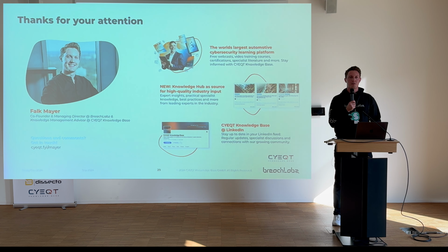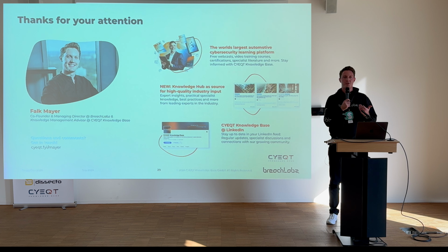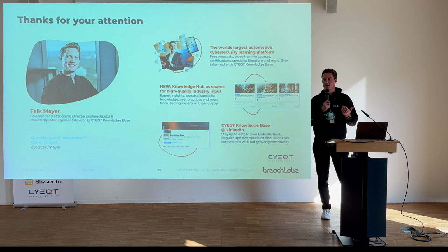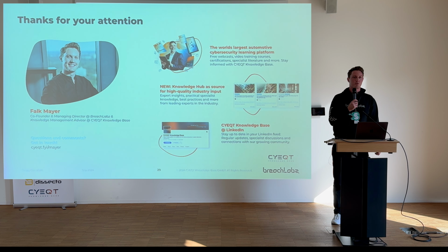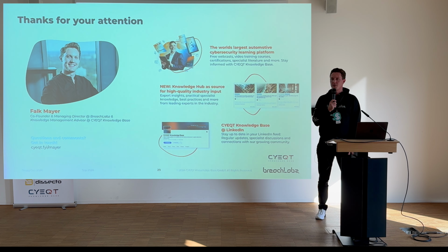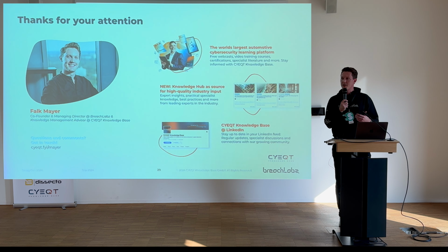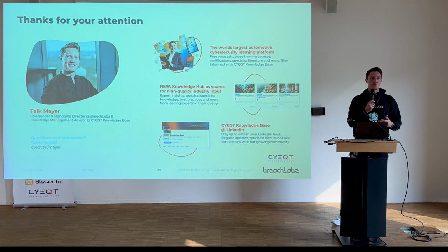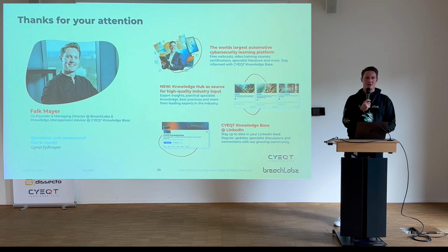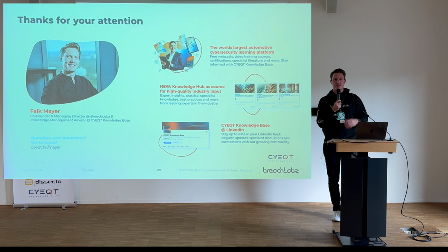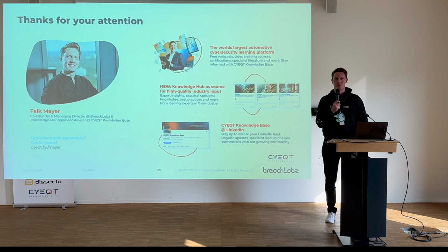Yeah, I think that's perfectly reasonable. Before you start the penetration test, you start with an amount of research on certain vulnerabilities, right? I think we're all quite aware, and I know that some of our customers in this room are still using TC2 controllers, for example, with the existing JTAG vulnerability that is, for example, just read after a certain period of time. So you have a certain amount of time after boot in order to dump the memory. This is why Infineon issued the patch for it, that you should protect your P-flash, for example, with a password, or encrypt it entirely in order to prevent somebody that has dumped the firmware from doing anything with it, like William has shown earlier.